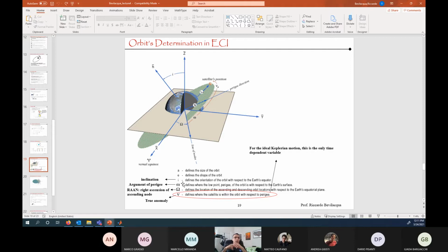The I, inclination, and omega, big omega, they tell you how the plane of the orbit is oriented. And then the last one, little omega, tells you in that plane which way the line of apse, the one connecting apogee and perigee, is pointing. Now, we have seen other angles, and so the way that those three angles are defined is you start from